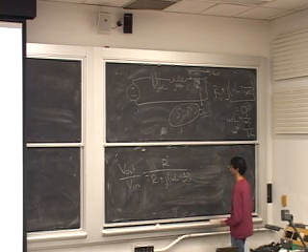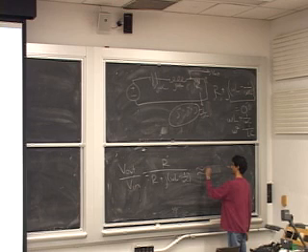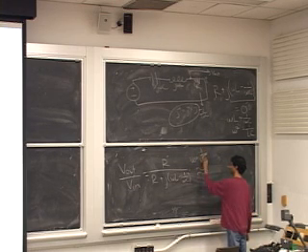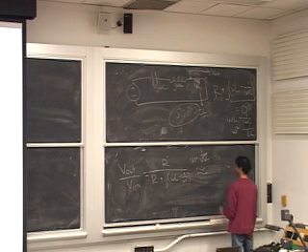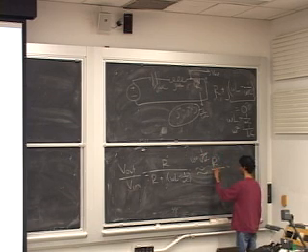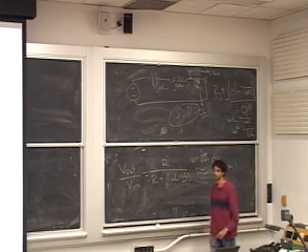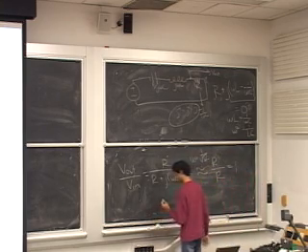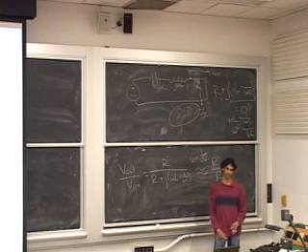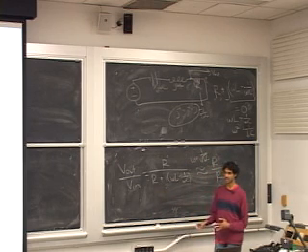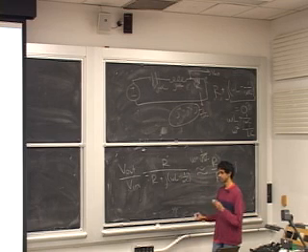So when omega equals 1 over the square root of LC, V out over V in is just R over R, which equals 1. So this is a special property of the circuit that says that at some particular frequency, we can see that these imaginary impedance effects cancel each other out.